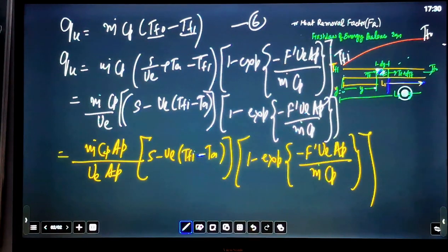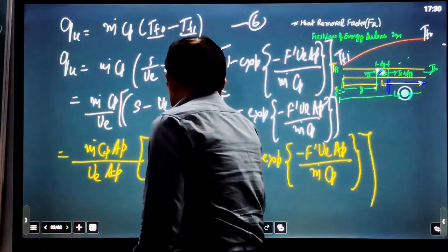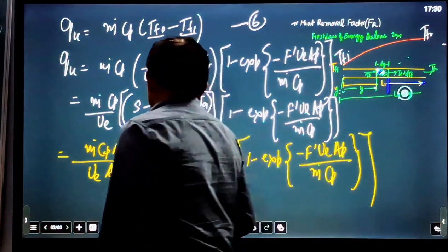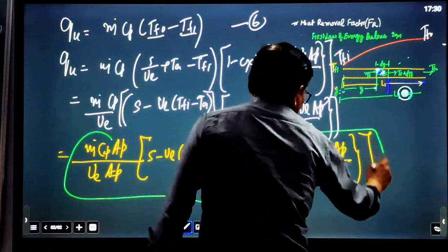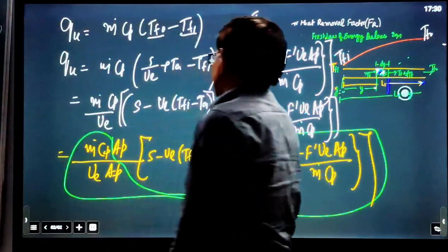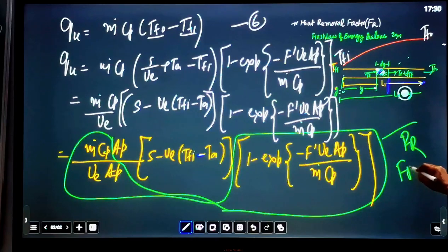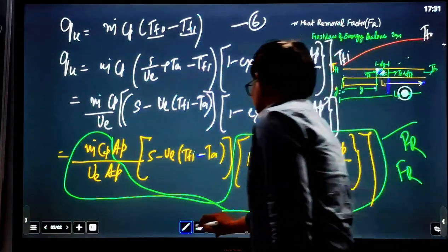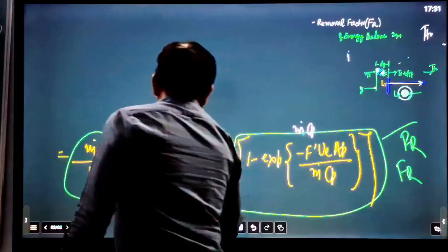Here we have to define the collector heat removal factor. Taking another color, this part we take out, and this whole part is converted into a constant that is known as the collector heat removal factor, Fr. So now writing this final equation in this form.